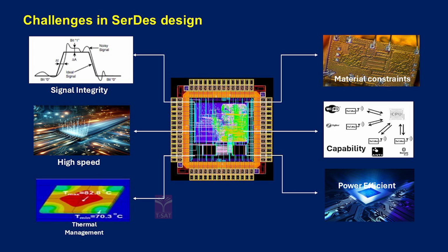We keep the device at a high temperature, 125 C. The industry grade temperature range is -40 degrees centigrade to 125 degrees centigrade. So we keep the device under stress at 125 for a longer duration. It's basically machine-based simulations we run in our setup, and then we see if it is performing well. Those are called our reliability checks or thermal management.